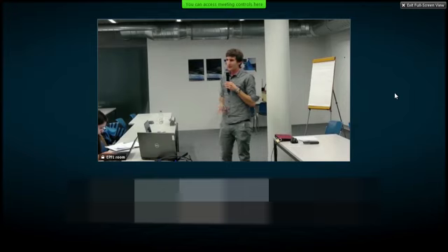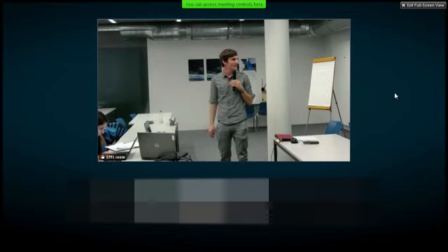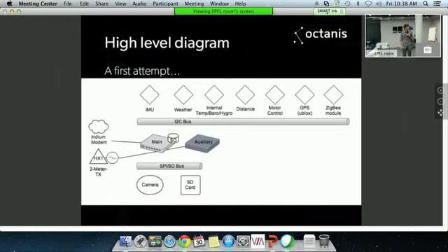So with all of that, we had our first diagram. Pardon the naive representation. This is not what we learned in this class, but that's what we had. This graph is mostly electronics focused. There's a main board in the middle with a bunch of sensors up here, also a camera and RF modules for communications, and some auxiliary board for the scientific payload, for instance. We kept going with this, and we designed a PCB with all these components, and most of it worked as well.